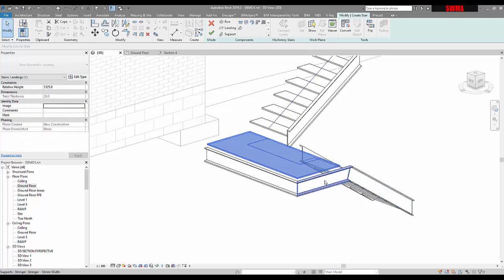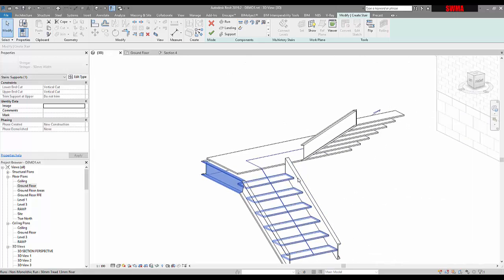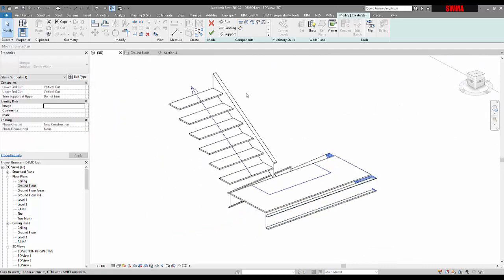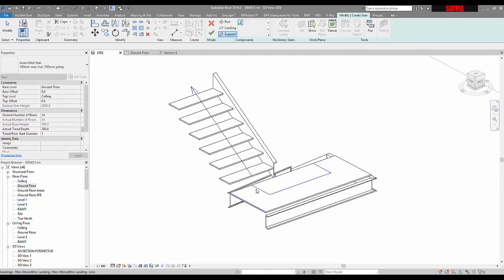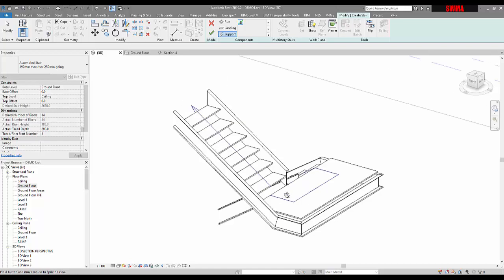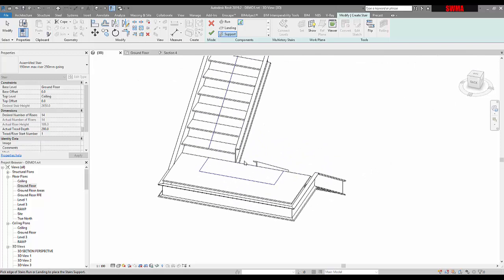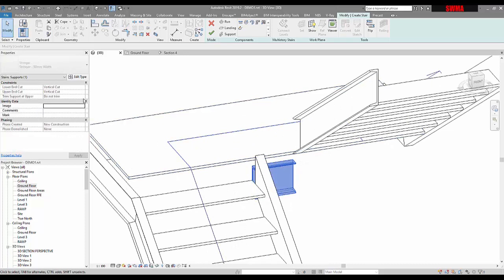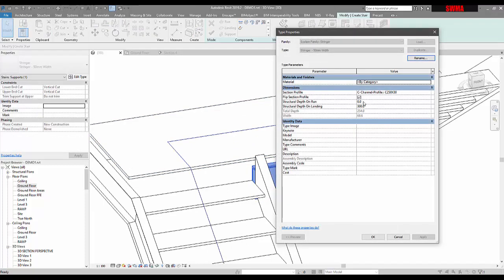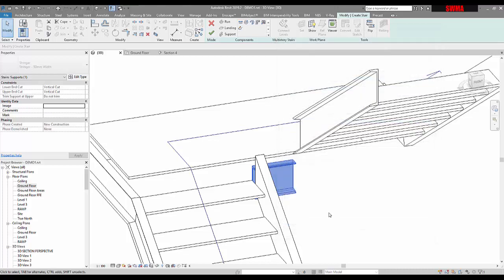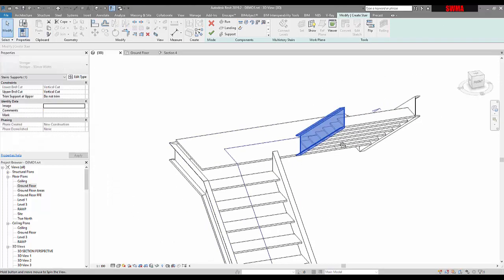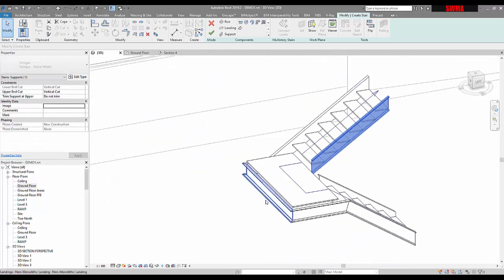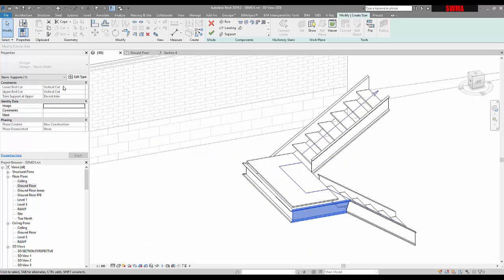The best way to do it is potentially to go and use things like Advanced Steel. Advanced Steel comes in the AEC collections and has a really powerful steel tool, and of course you can work with the fabricator to manufacture it directly from the model. So this is kind of good for design intent, but depending on the codes and where you are working in the world, it can be a little bit tricky. You can sort of see here we're getting into some problems with how that might work at that particular junction. So definitely good for design intent. You can tweak it, and get some good results.